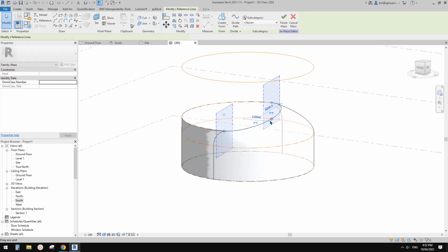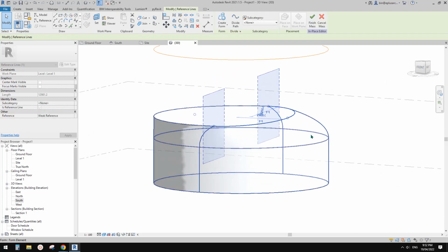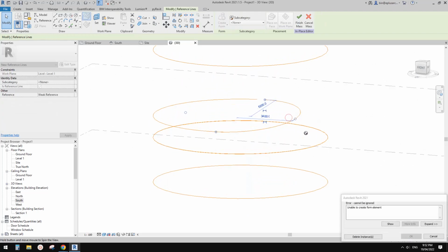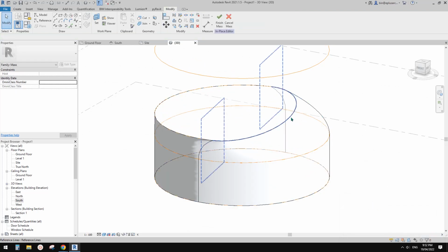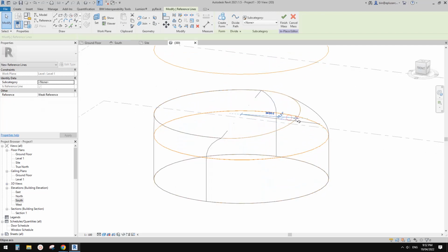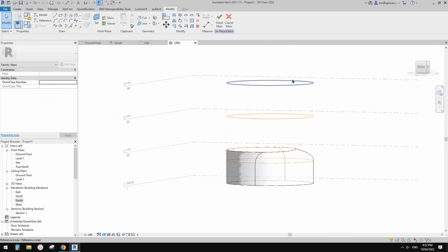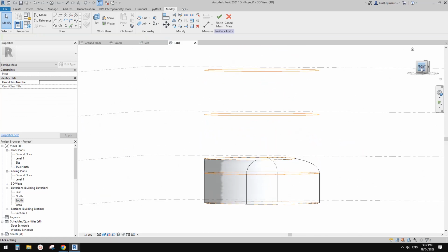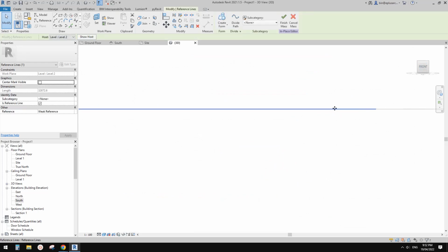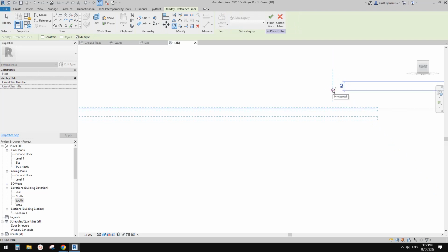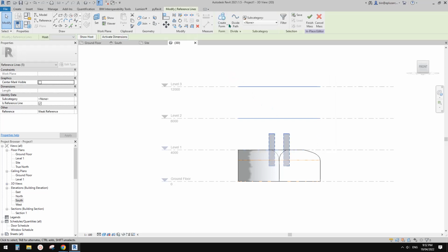Also, you can always change this shape or change the form, massing, by adjusting the reference lines. But yeah, all good. And it's the same for the top part. What I'm going to do is copy this one down, zooming first, copy it down, shift by 5 mil, and then select these 4 and create a form.